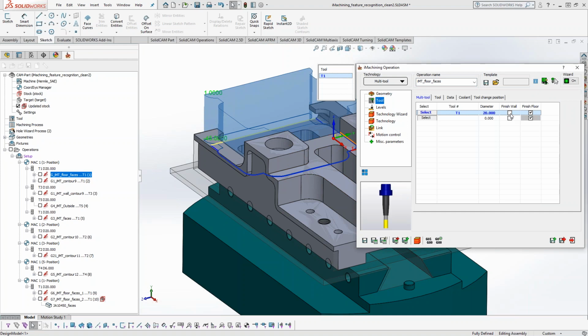If you want to 3D rough the entire thing, you can 3D rough the entire thing, go to 2D iMachining and use the feature recognition stuff. And for all of you that are using SolidCAM and iMachining already, all the tools are still here for iRough, iRest, and iFinish, and you can still program that way if you like, but you don't have to do iRough, iRest, iFinish, and link your operations manually anymore. This is all done automatically in the new feature recognition.